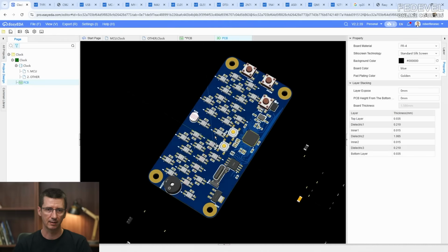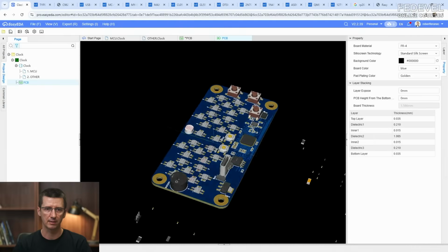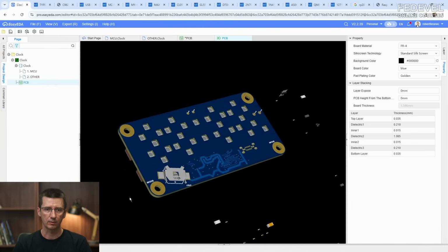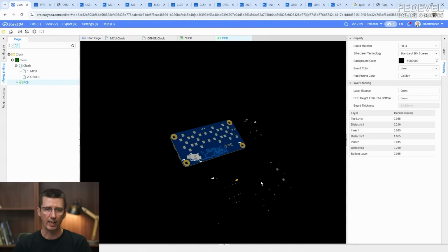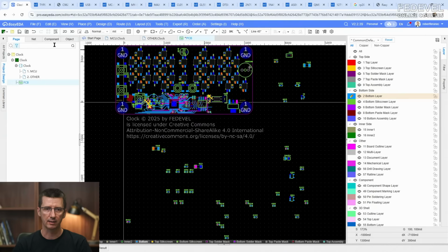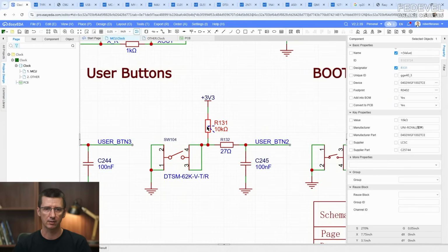You can see the light sensor is right now at the bottom, but then we will place it on the top. Again, I'm going to explain why, because when we will be ordering the PCBs, then we can order only assembly of the bottom layer, and it's going to be cheaper. If we order assembly of 2 layers, it's going to be more expensive.